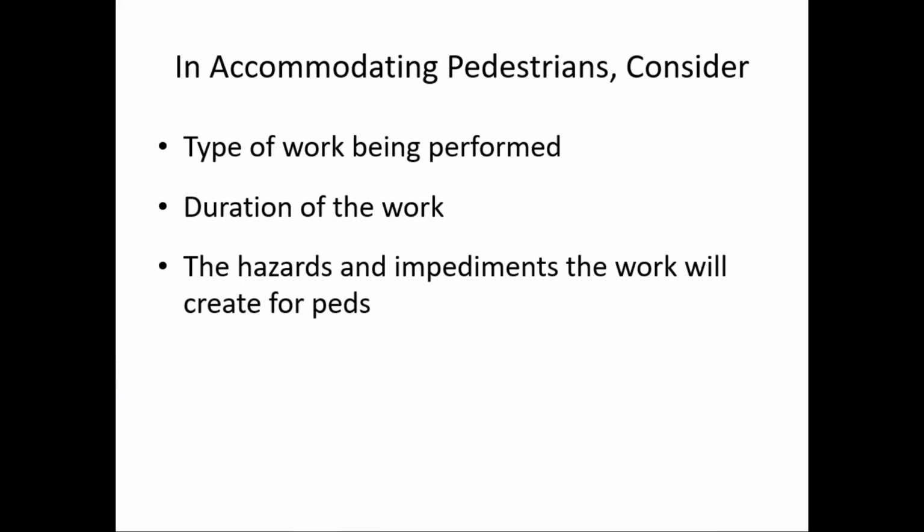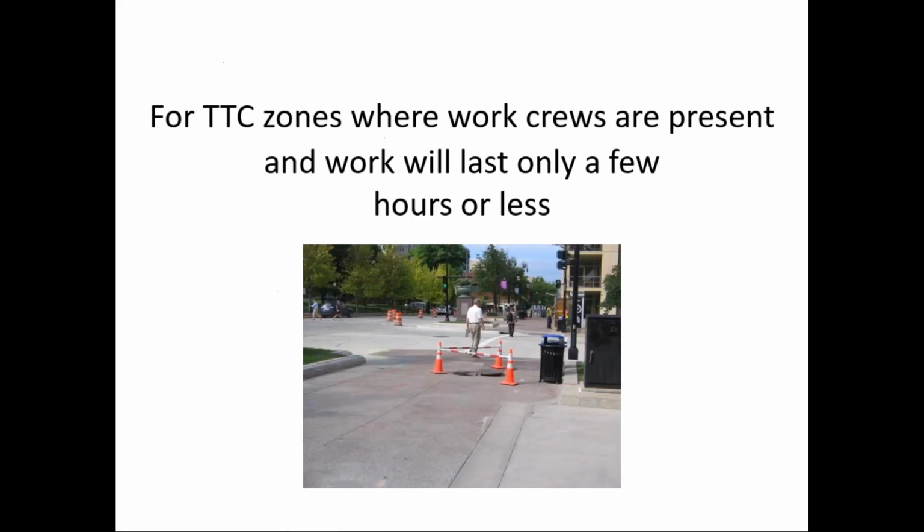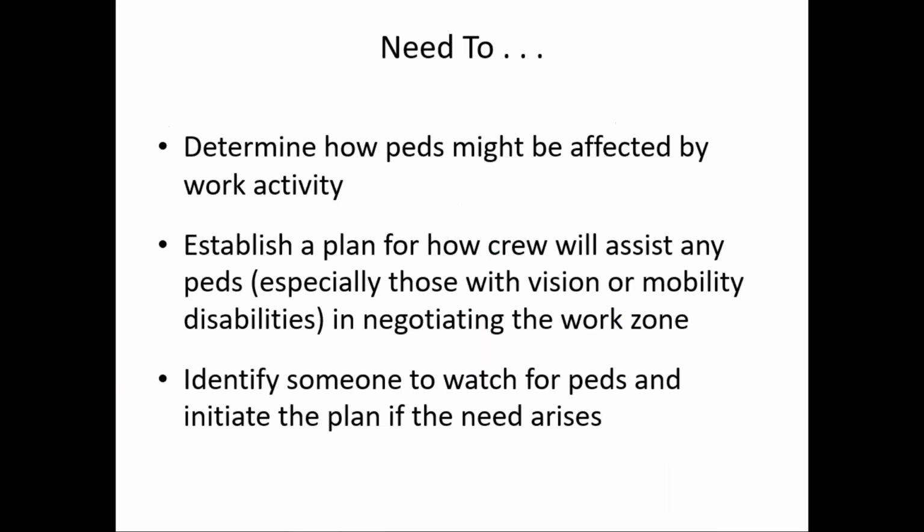So when we're talking about accommodating pedestrians, I would consider the type of work that's being performed. What's the duration of that work? What sort of hazards and impediments will that work create for pedestrians? I showed you this image earlier. Probably the work crews here were just going to be there for a few hours, or even less than that. So I would, before work started, determine how pedestrians might be affected by that work activity. I think we mentioned that earlier.